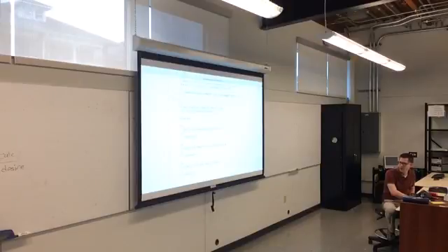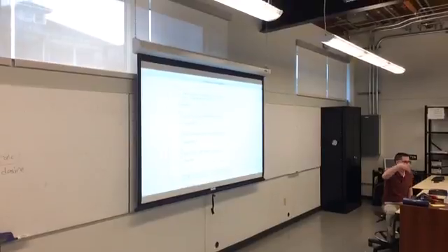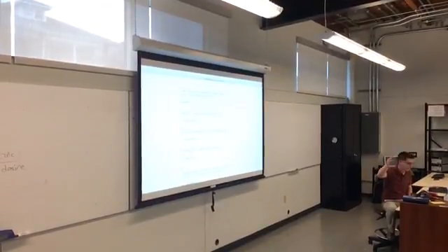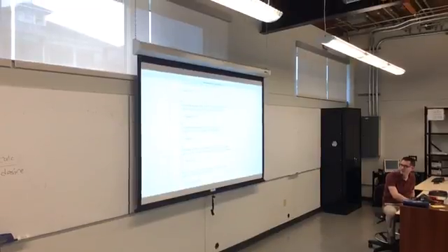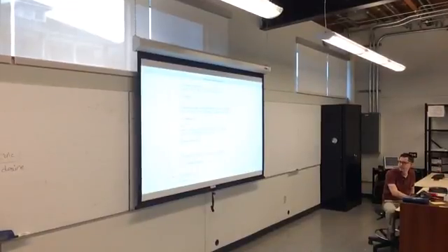And then I have given you a couple functions here that will be useful. Is the data valid? Is the bus busy? Is it NACK? And you can see their implementations here. So you've got to do set up clocks. You've got to do set up GPIO, I2C. I even gave you this thing at the last, which does the abort. Make sure that's last.